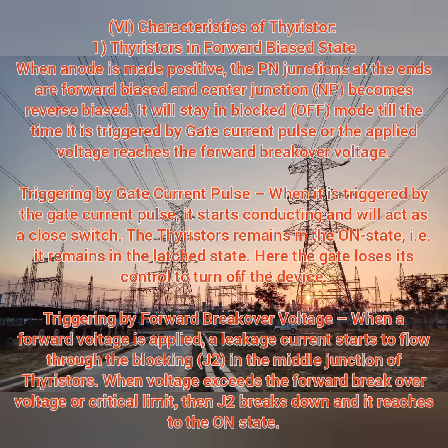First, forward biased condition. When the anode is made positive, the PN junctions at the ends of your thyristor will be forward biased and the center NP becomes reverse biased. So it will be in an off condition till the gate current or gate pulse is induced in it, and then it goes into forward biased conduction.